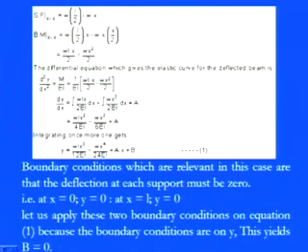So now you have the bending moment. Go for the basic equation for the deflection, that is M by EI equals d2y by dx squared. By keeping that value, you have d2y by dx squared equals 1 by EI, which is the constant, and M is equal to WL into x divided by 2 minus Wx squared by 2. Now by integrating, one can easily get the slope equation dy by dx, which is equal to the integration of WL into x divided by 2EI into dx minus the integration of Wx squared by 2EI into dx plus A.